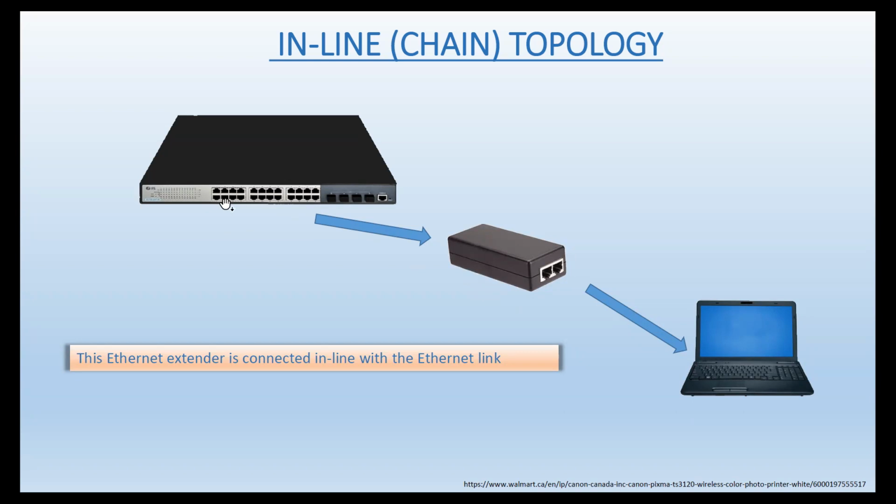Some of the switches have all the ports capable of PoE. Some of the switches have no PoE capability on any of the ports, and some of the switches would be kind of economical. By that I mean maybe the first 8 ports are PoE capable, and the other ones are just signal. So you gotta watch what you're buying, and when you're specifying things, running specs or designing a system, you gotta pay attention to that kind of stuff.